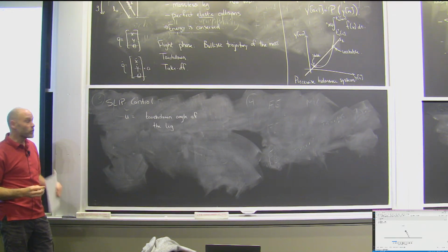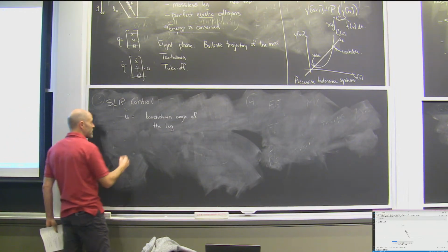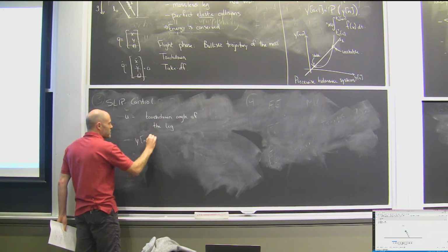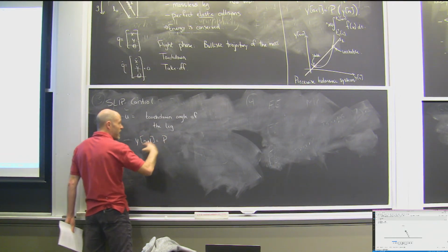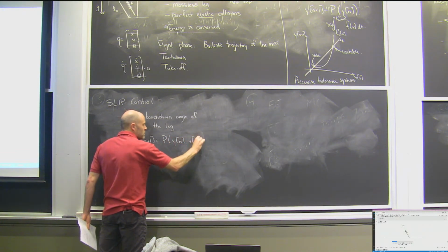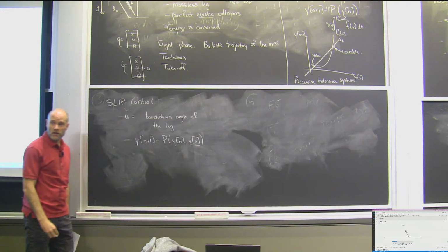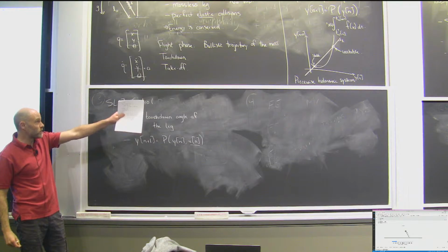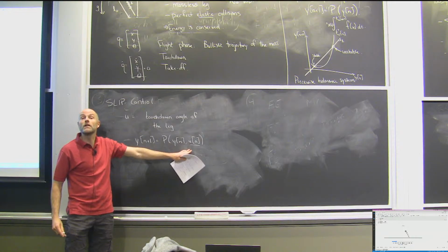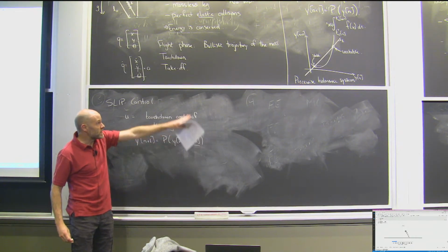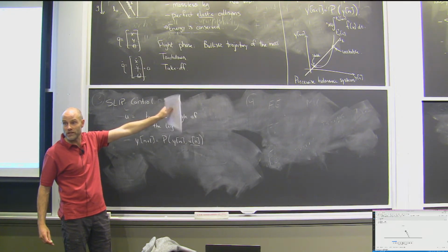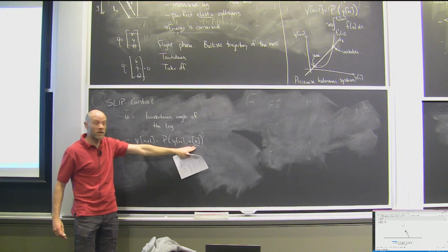So if we were to be more explicit now about this Poincare map, we could write it as y_{n+1} is some discrete map integrated over the cycle of y_n that's dependent on my control, my touchdown angle control. I drew it there for a fixed choice of touchdown angle, but I could actually choose a different angle at every step and potentially change the rate at which it converges, even move the fixed point. I can change that map by changing my touchdown angle.